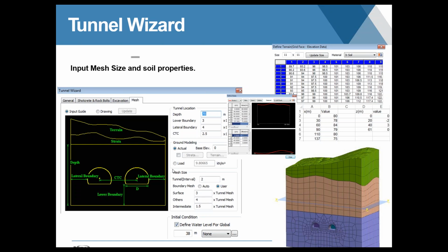And if you wanted to, you can make it just a square model, completely flat, or if you wanted to consider information about the terrain, you can, in a very simple table format, just type in these values, let's say for one of the strata layers, to change the location of the surface in both axes. Or like we did in the last example, you can also import grids with information about elevation.